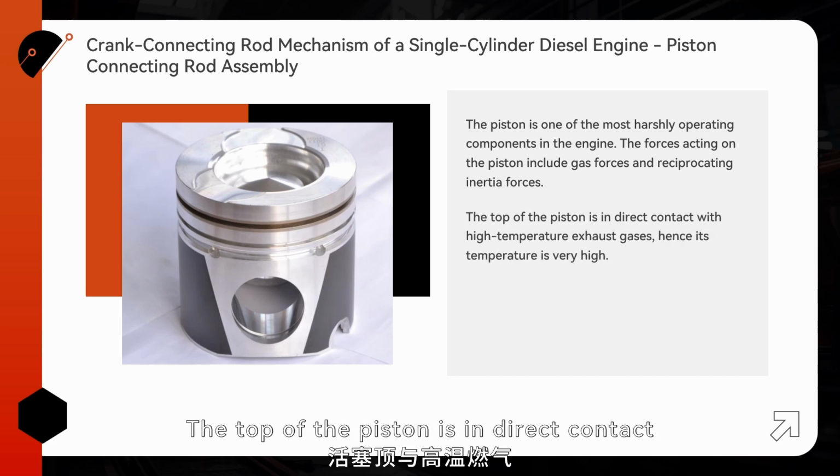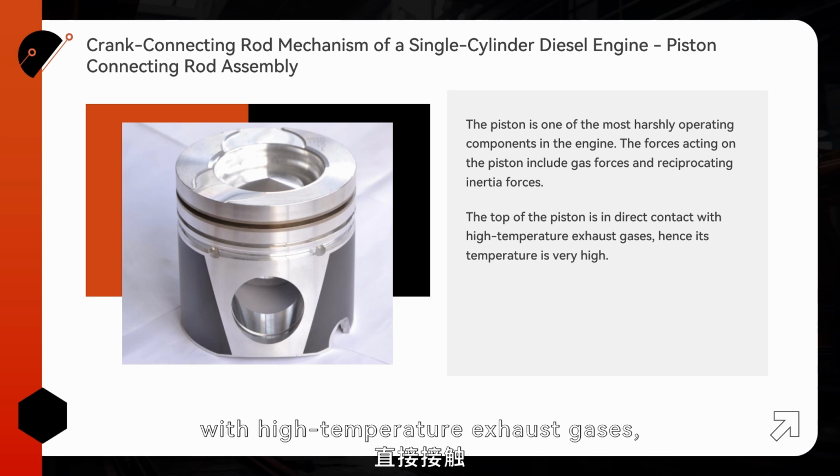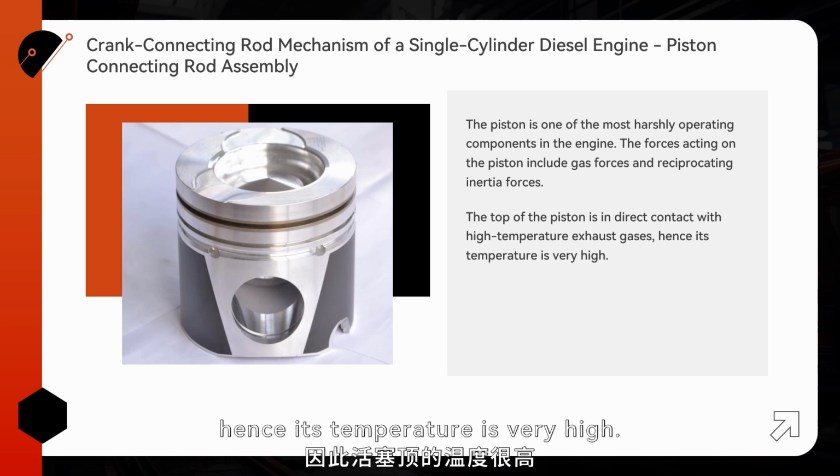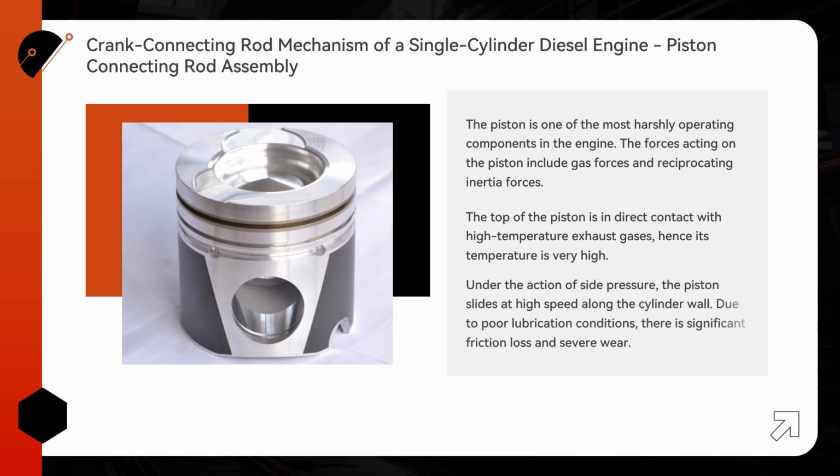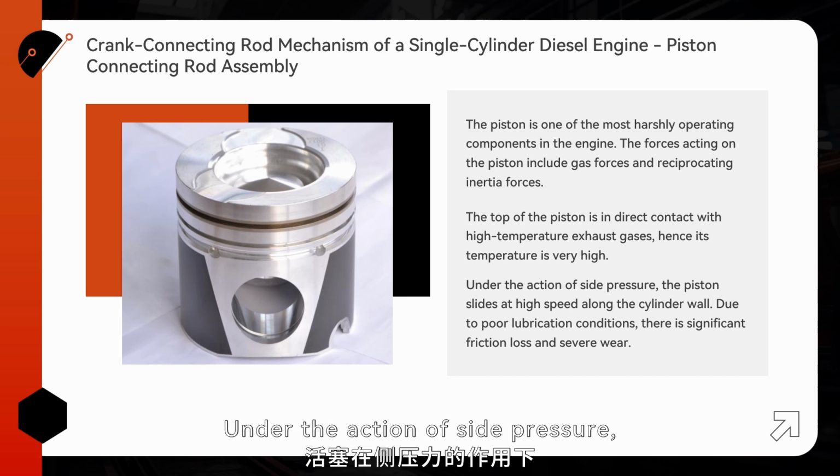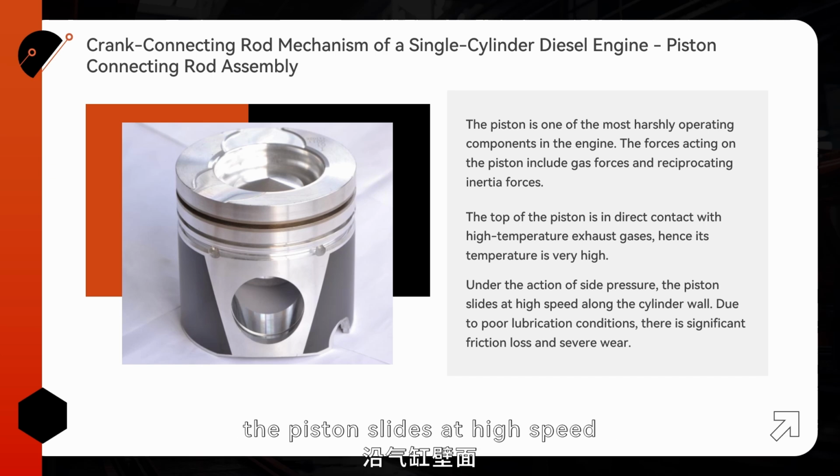The top of the piston is in direct contact with high-temperature exhaust gases, hence its temperature is very high. Under the action of side pressure, the piston slides at high speed along the cylinder wall. Due to poor lubrication conditions, there is significant friction loss and severe wear.